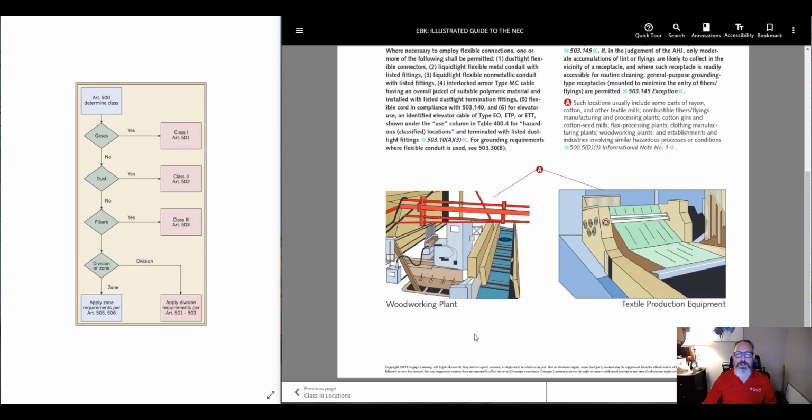The switch, it got full of sawdust, the enclosure on the outside of it. And I'm pretty meticulous about my tools. I blow the dust off every single time I use it, clean it out. But the dust was just kind of getting into a little hole in the back where the wire came in, and it just filled it up and caused it to short out.